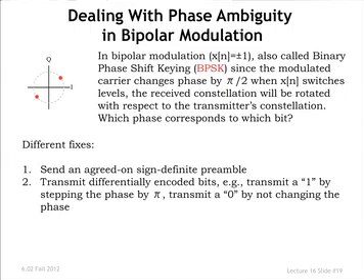The only problem here is if you've got uncertain phase and delay, you actually don't know which of these 2 points corresponds to the +1 and which corresponds to the -1. So there's that additional ambiguity that needs to somehow be resolved. And the different procedures you might use, you could, for instance, have some preamble with a sign that's agreed on and use that as a basis for figuring out which is a plus and which is a minus.